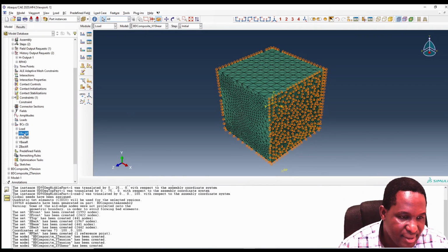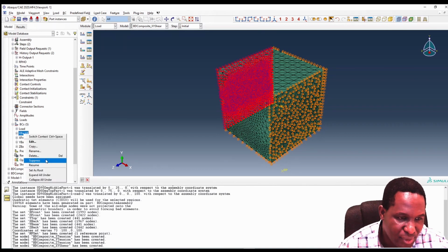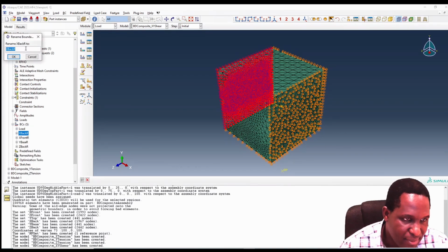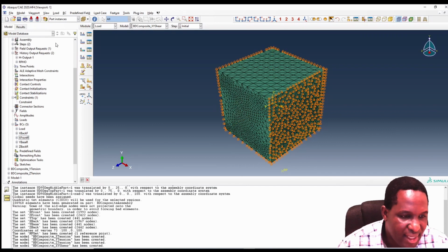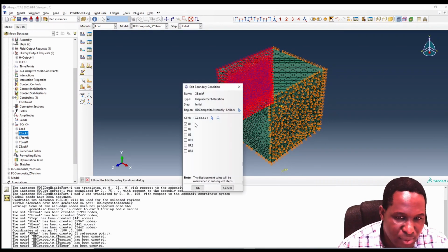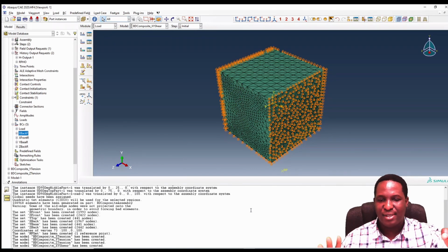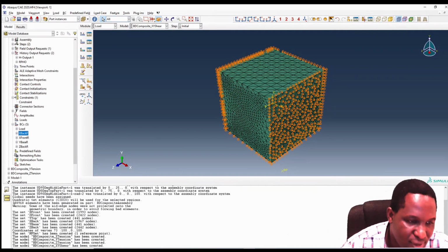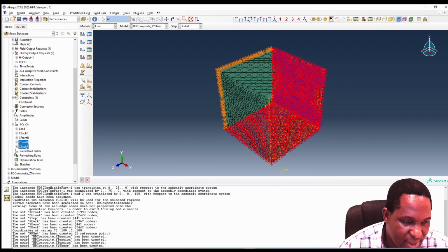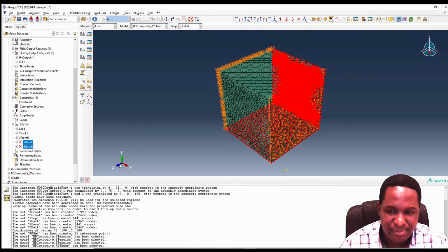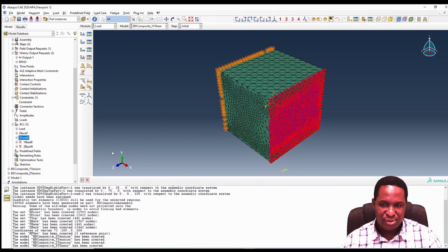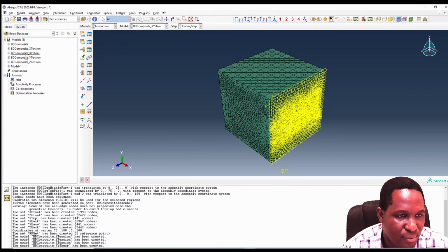Now the x back would have to be renamed to x fixed, and that x back would have to constrain in xyz direction. So you hold it firmly there and you slide at the front. All the other bits, yz and y base, will have to be suppressed. Okay, so we don't need those. So that's that for xy shear.